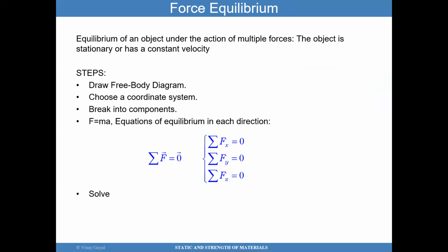To solve problems in statics and mechanics of materials, we can apply force equilibrium, which can be derived from Newton's law. The equilibrium of an object under the action of multiple forces can be determined. The summation of forces equals ma, but here I have used force vector. That can also be looked at on a component basis. So I have summation of forces in the x direction alone, in the y direction alone, and the z direction alone. You can do it multiple ways, but in general, these are the steps you'll be using.